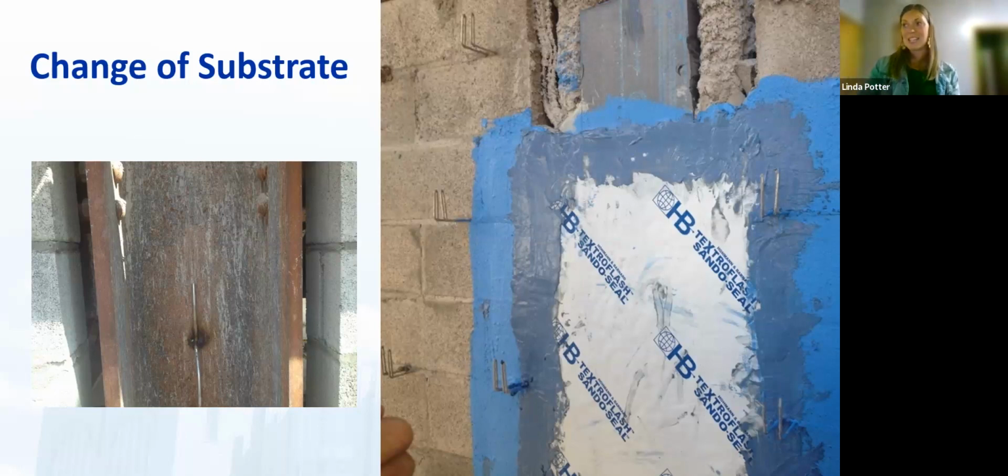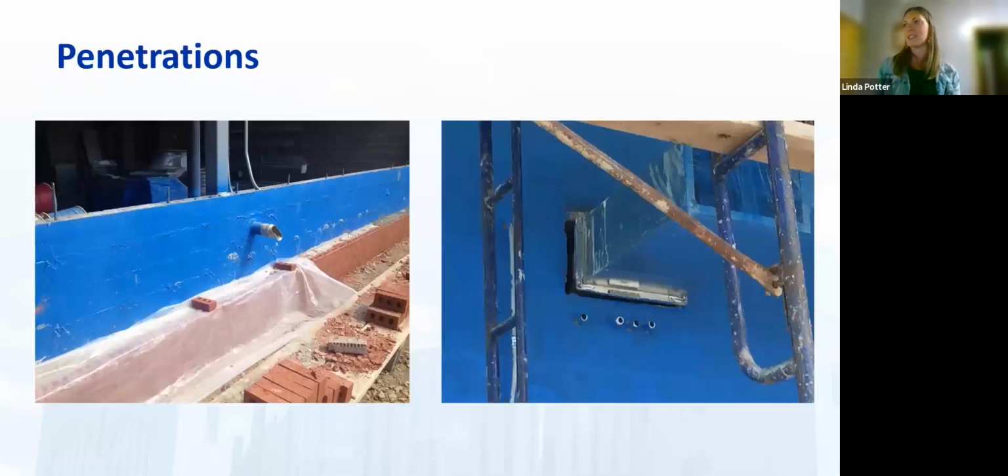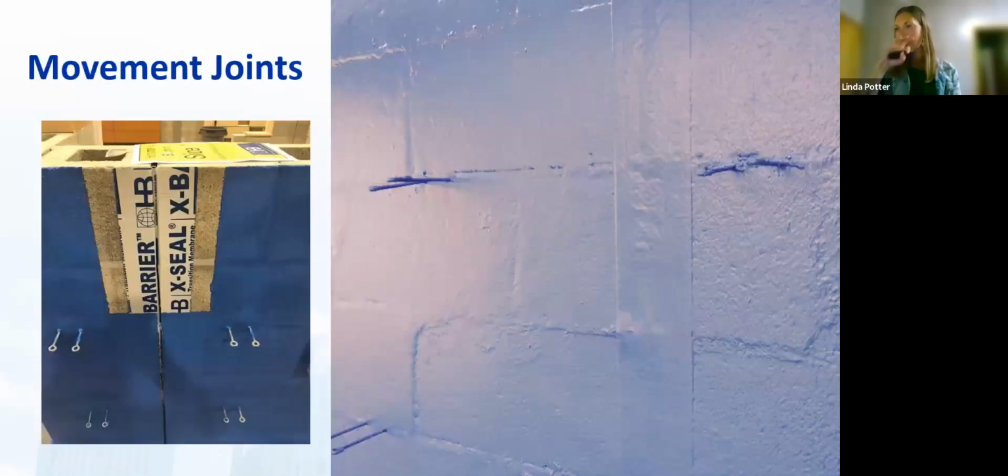But this type of thing can slow down a project if in the middle of it we're just now deciding because we ran upon it, and now we've got to stop for a week because we have to let everything cure. We have to figure out what we're doing, and then let everything cure so that everything can be built out, and we've just lost time. We just don't have time now, right? More on penetrations. Some are square, some are round. Make sure they have a plan for how they're going to fill those in.